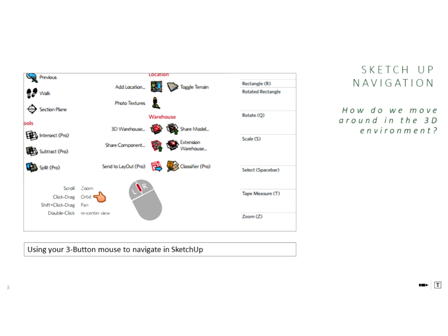And then when you're clicking and holding your mouse wheel down and you hold your shift key at the same time, it will bring up the hand or the pan tool to go from side to side without actually spinning in an orbit. And you can double click on the mouse wheel to recenter your view. It'll recenter around just all of the geometry on the screen so far, which is the same as the zoom extents button on your keyboard, but a quicker way to do that.